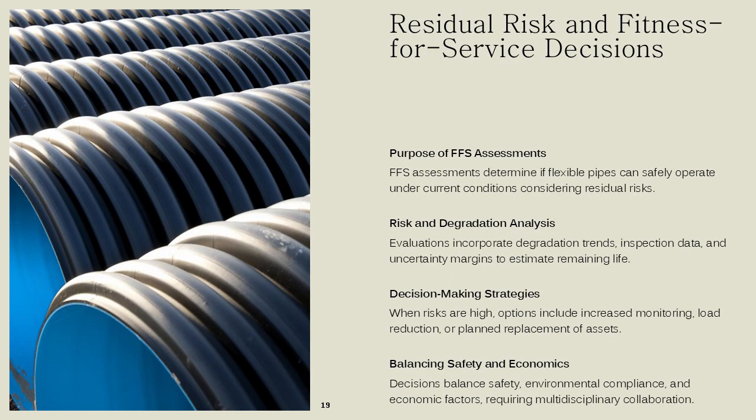Fitness for service, FFS, assessments determine whether a flexible pipe can continue operating safely under existing conditions. These evaluations consider residual risks after implementing design and operational controls, factoring in degradation trends, inspection findings, and uncertainty margins. Analytical models estimate remaining life based on fatigue cycles, corrosion rates, and polymer aging, while empirical data from monitoring systems validate these predictions. When risks exceed acceptable thresholds, options include increased monitoring, load reduction, or planned replacement.